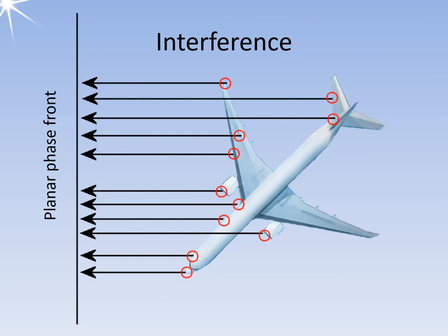All parts of the reflected or scattered energies have a different distance to the phase front. All depend in varying degree on the target aspect angle as seen from the radar. This results in different phase positions due to the runtime differences. These individual parts can either subtract, destructive interference, or add, constructive interference. Another aspect angle of the same aircraft results in other distances and thus other interferences.